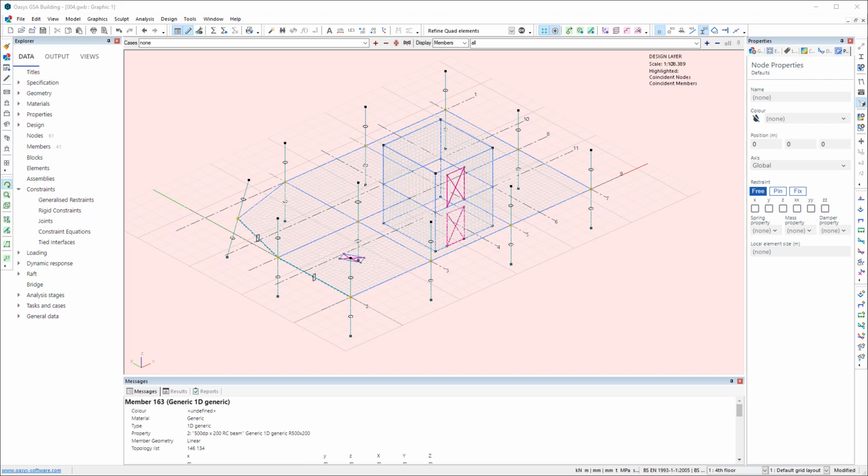So this is the last in the series of the videos, at least for now, and I'll basically end by looking at rigid lengths and offset beams. These are things I covered in my lecture last term, so I'd suggest you look back at the notes for that, and also a bit on section modifiers and changing use of materials so you can alter the stiffness of the elements in the analysis.